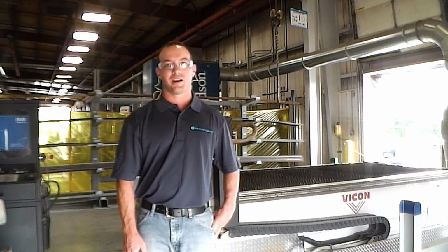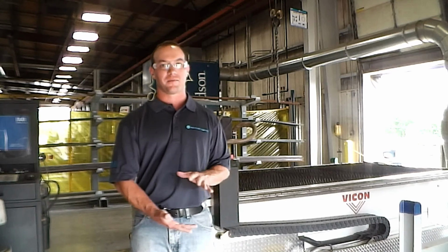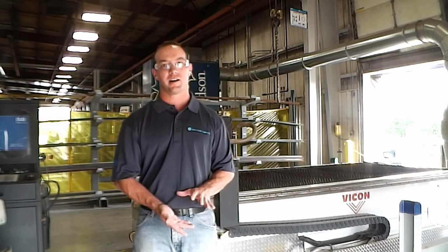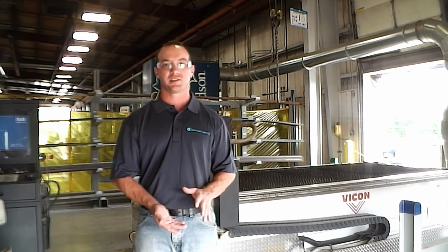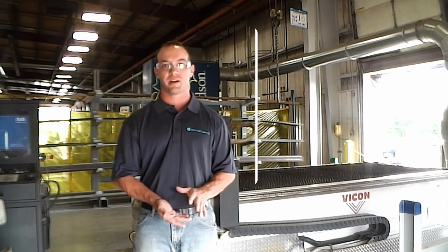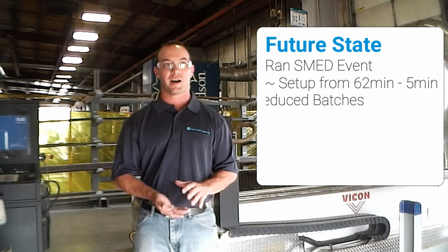In our cut shop, we identified changeover time as an area that needed improvement. Due to our different sizes of plates and the changeover time, we are batching parts for products. To reduce this batching, we did a SMED event at the plasma table. The SMED event reduced our changeover time from 62 minutes to 5 minutes.